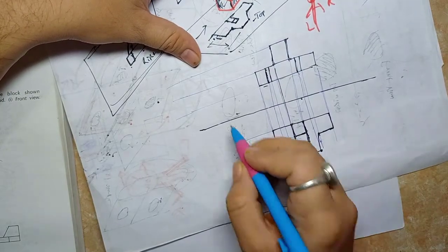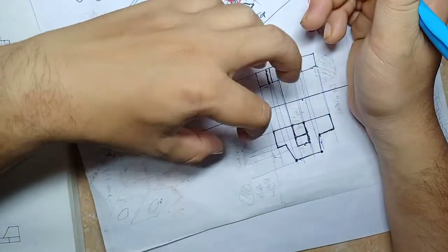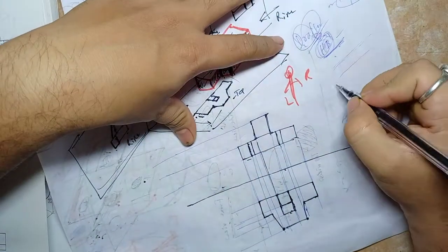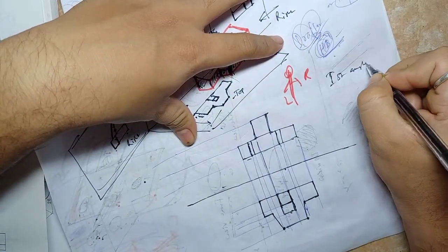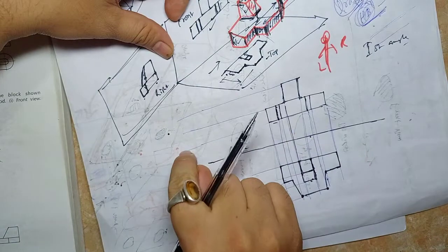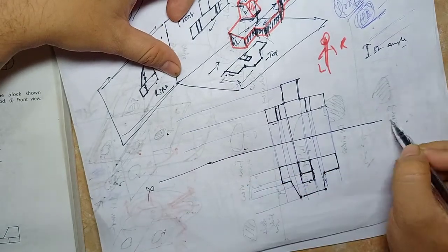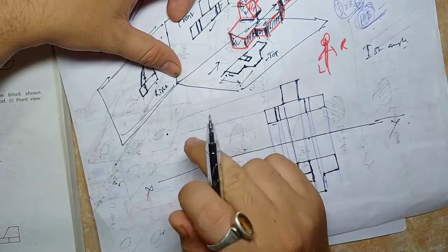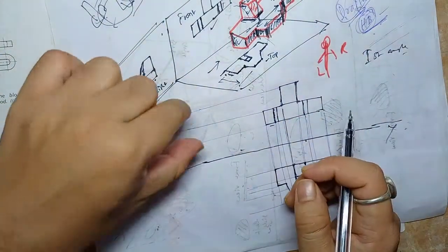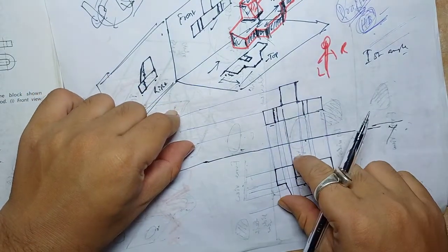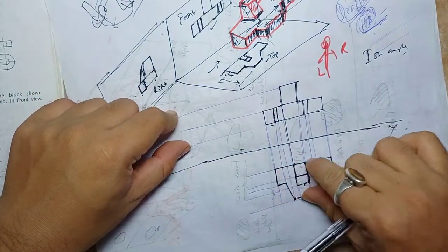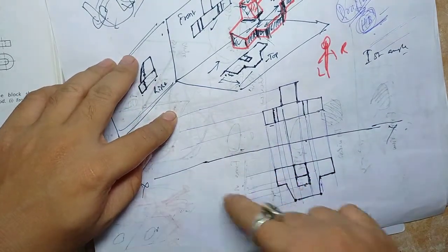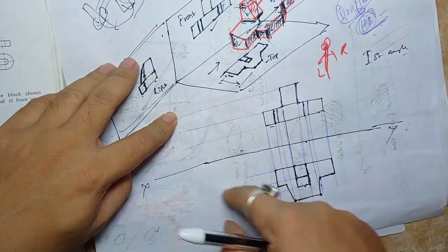Now let's see, we have got these lines here, we have got these lines here, but what is the use? No, but we know that for, let's say, first angle projection, your right side view will come above your xy line, right, above the xy line. So it will come here. Okay, so we must obtain your right side view from the front view and top view. For that we have to take the projection lines of the top view up to this portion. Okay, the xy line, it should go that side. Okay, but there's a method.